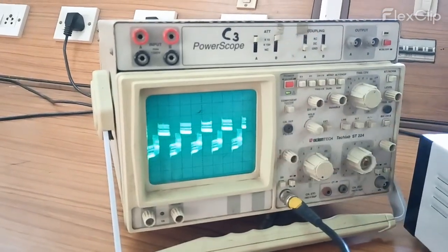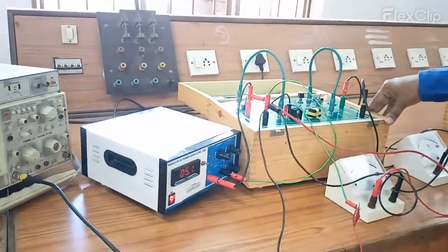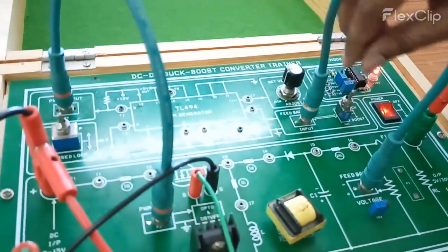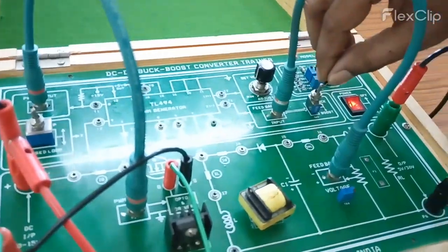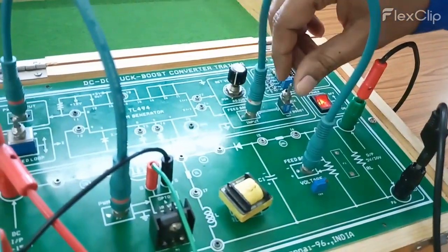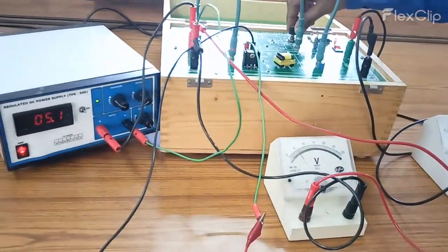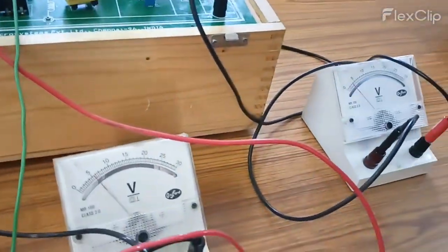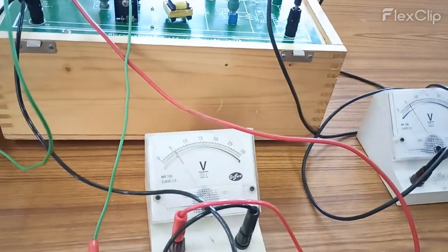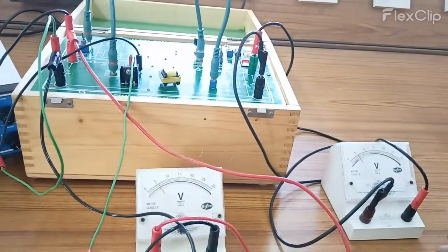So this converter is giving the output voltage. Okay, so this is in boost mode, and we can switch this to buck mode also. So here we have a provision to switch the operation of this converter from boost to buck or buck to boost. So now I am shifting this boost operation to buck in order to validate the results. So here you see, when you vary the duty ratio, it can give an output voltage which is less than the input voltage. Okay, so the output voltage of the converter will be less than or equal to the input voltage. That is called buck mode.